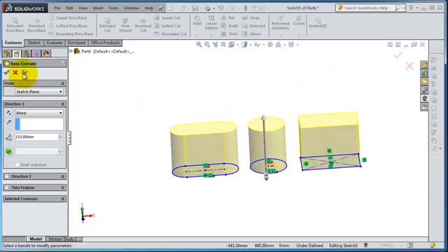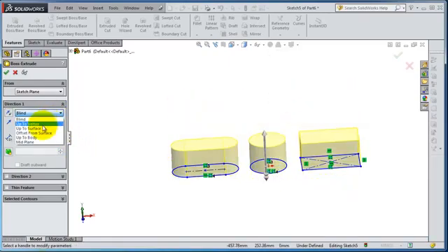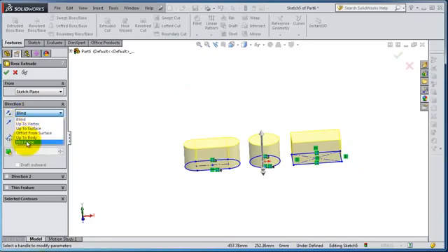And now let's move to the left menu. Here you have the type of the extrude. Blind is just where you can move it the way you want, and here you have other options. You have up to vertex. For example, if you have another body in front or other edges, you can select the vertex, and if you have a surface in front, you can also select that surface, and up to body. But in this case, we have the mid plane. You can start working with it.